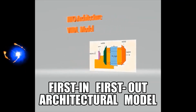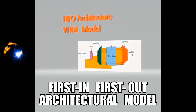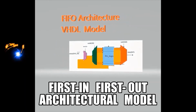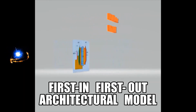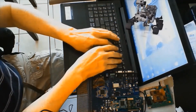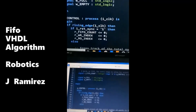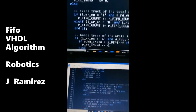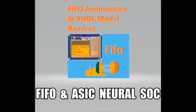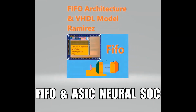In order to write data into the FIFO, first in, first out, first push the data onto the data in bus and then strobe the write enable input high for 1 clock cycle. It will write whatever is on the data in into the FIFO's internal memory. Writing in bulk, the write enable signal is left high while changing the data on the data in bus each clock cycle.